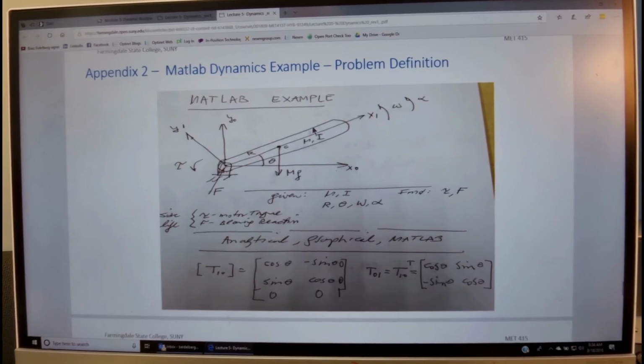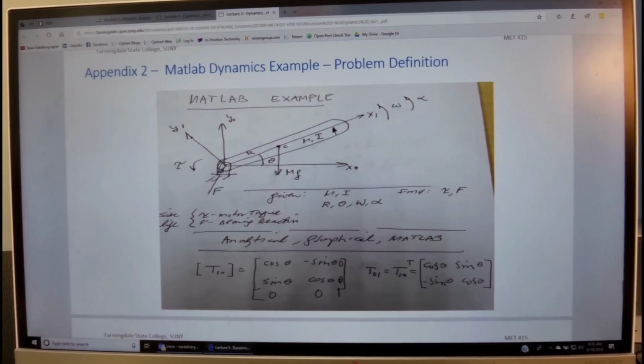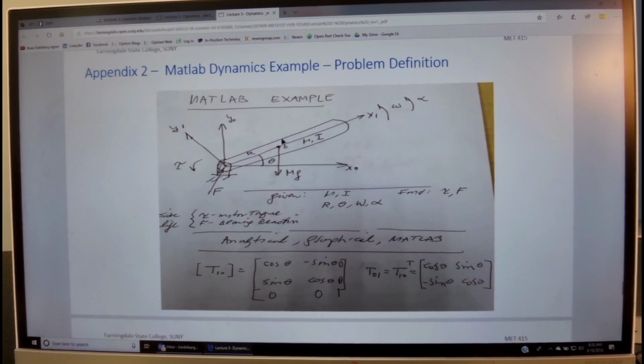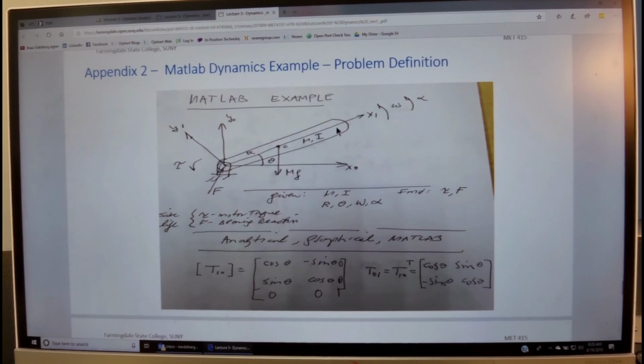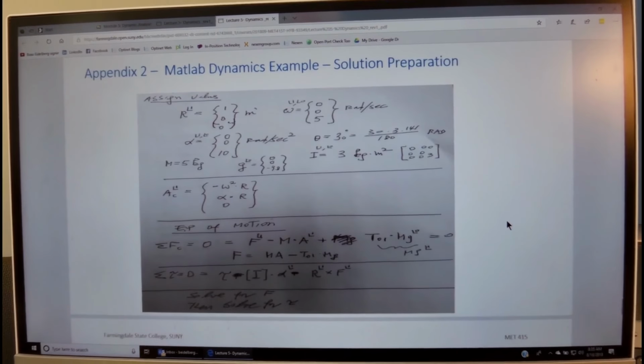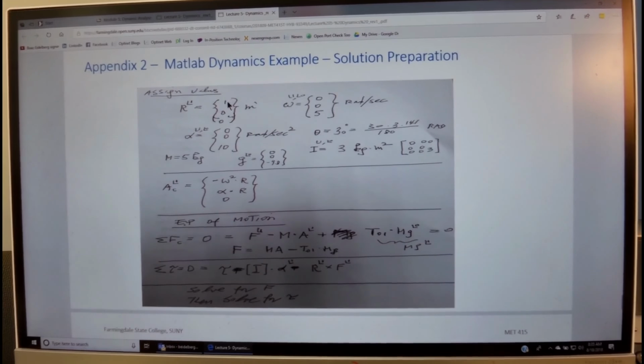This is a simple example that shows a single link which has various parameters, and we go also through the process of coordinate transformation. In this particular case, given the angular velocities and acceleration, mass and inertia, we're interested in the reaction force and the motor torque, so we can go through that derivation and write each one of these vectors, write the equilibrium of both